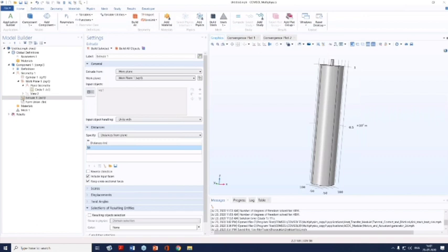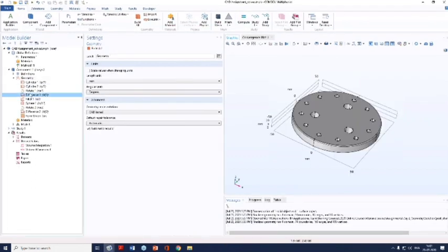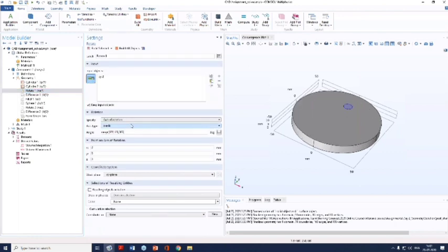How to create shadow structures we have already discussed. The rotate feature also we have discussed just now. Now you can use the rotate feature in the assignment section also. By using the rotate feature, we have given the axis of rotation, that is the Z axis. Around that axis we want to provide the point on the axis of rotation, that is where that axis is located. Here it is the center of the object itself, and then you can provide the angle by which you want to have that rotation happen.